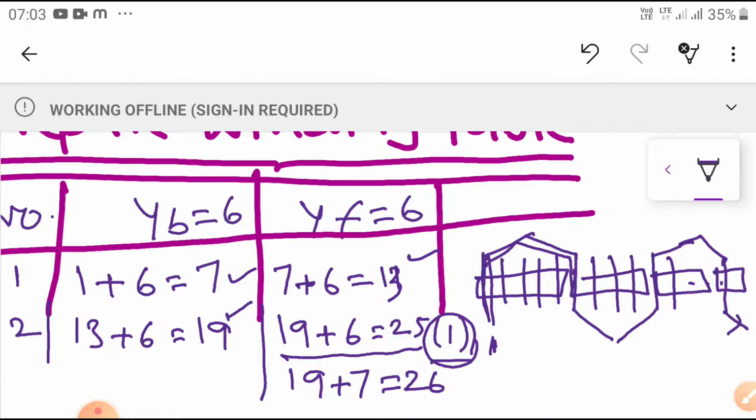Adding 6 to slot number 19 gives 25, which is slot number 1. But a coil side is already placed at slot number 1, so there is no scope to add. Here the constant is one slot for one conductor only, and that slot is already filled with conductor 1. Once again, AC winding is an open winding, not a closed winding.